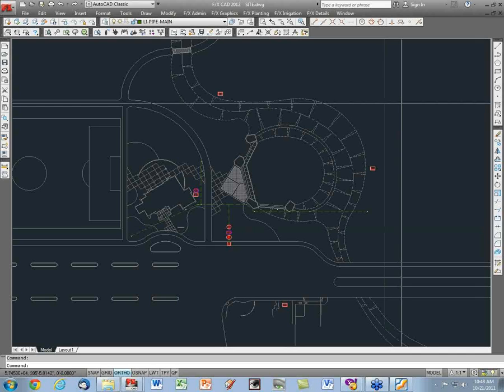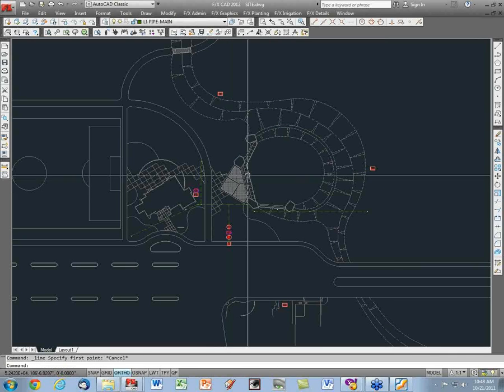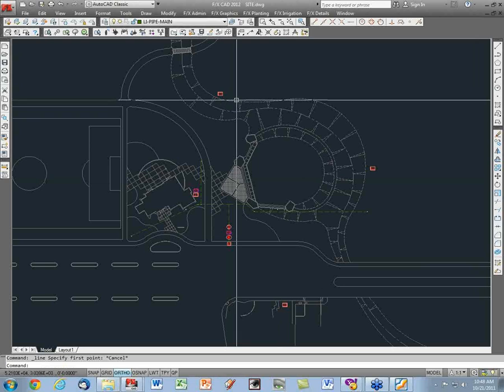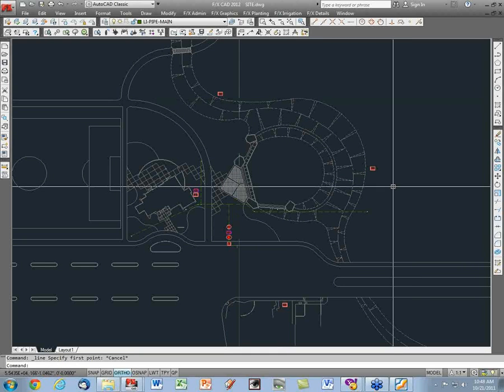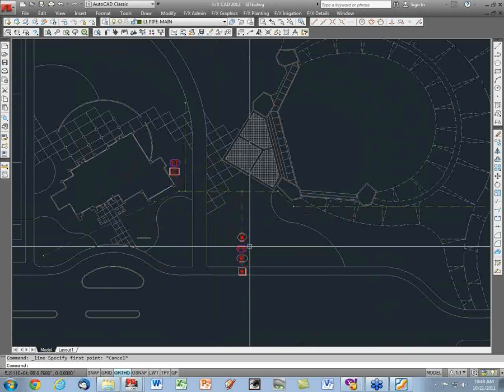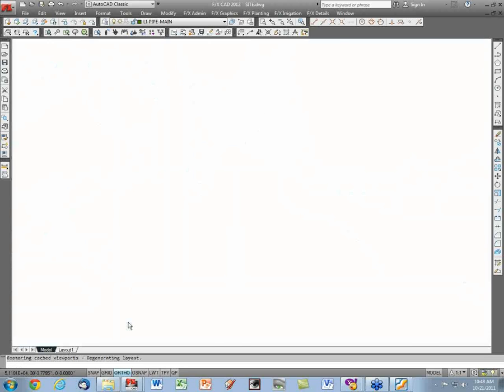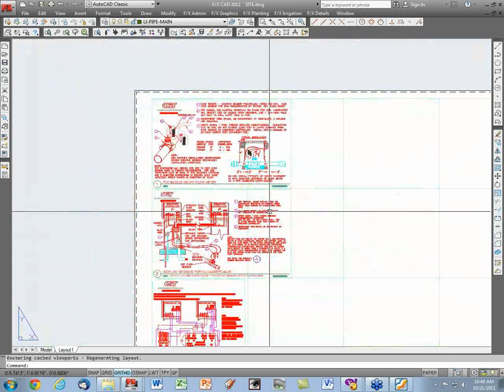What you're going to be doing with these is obviously bringing pairs of wires to each controller. Now, whether you do that as a spoke or whether you do it as a serial type of thing depends on what's the easiest way to show the wiring, or what's the path of the irrigation zone lines or main lines or things like that that would make the wiring path more convenient for the contractor. But in the detail, it does tell you the numbers of wires necessary, and you'd have to incorporate that into the construction instructions. Okay.